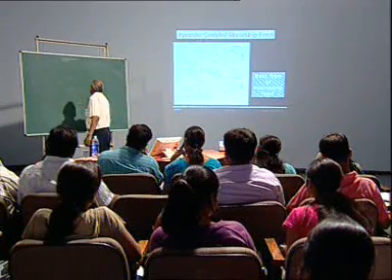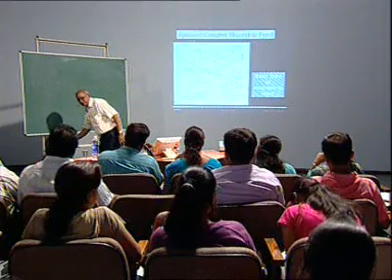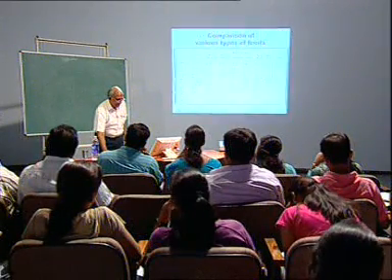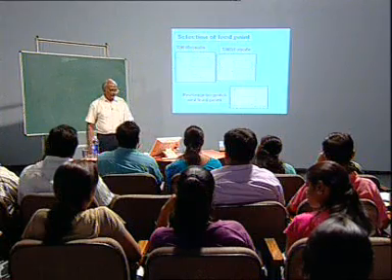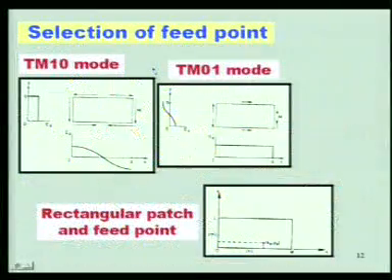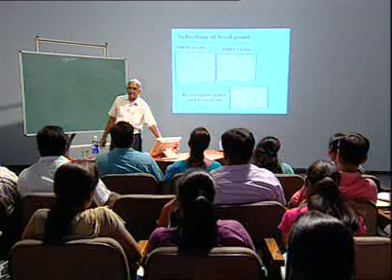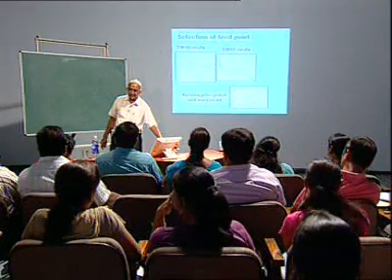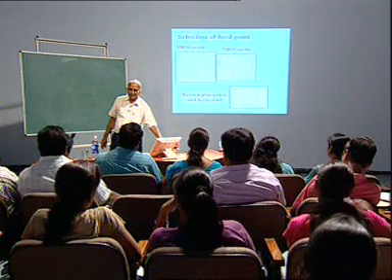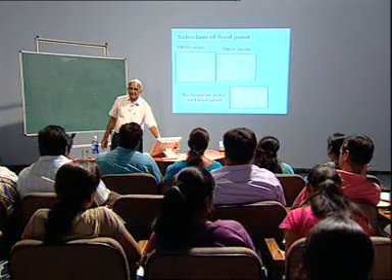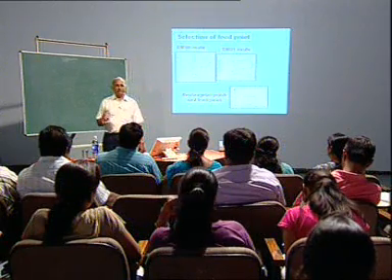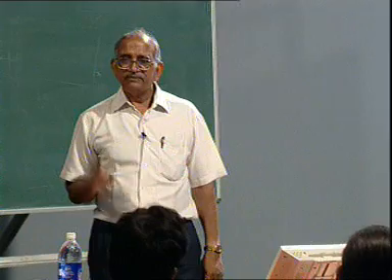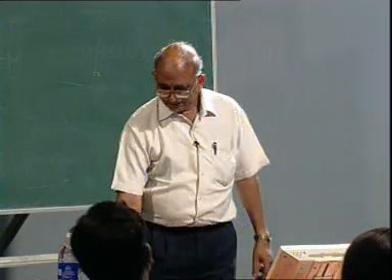we have looked at the field distribution, let us say for the 1-0 mode, if we go back, yeah. This was the electric field distribution for the desired mode. Electric field is maximum here, 0 here, again maximum over here. But the magnetic field distribution will be just the opposite. It will be 0 over here, maximum here and 0 over here. And in this case, the coupling between the slot and the patch is a magnetic field coupling. Okay.